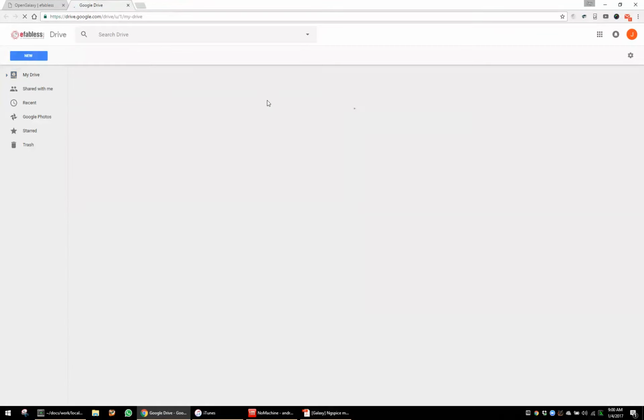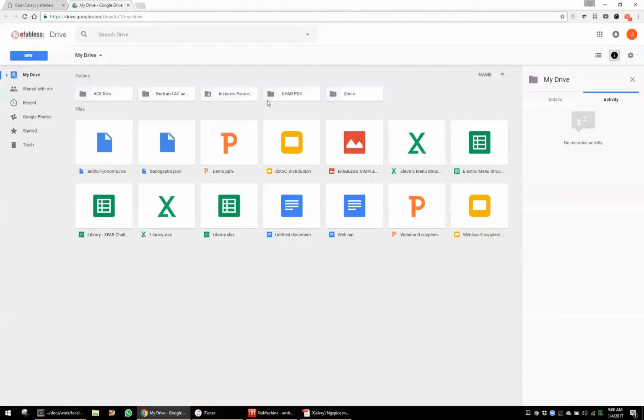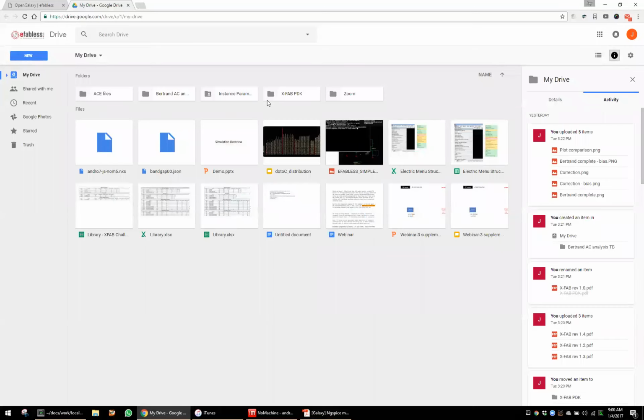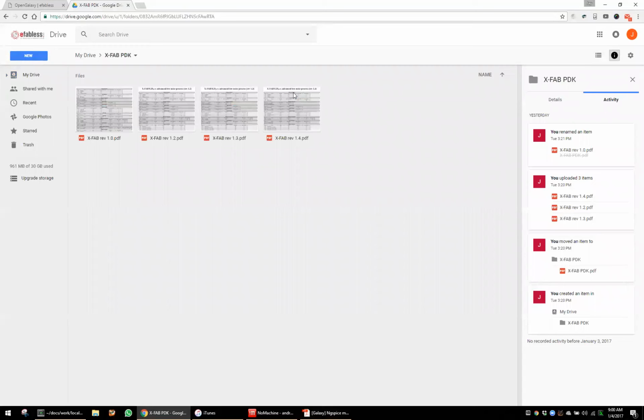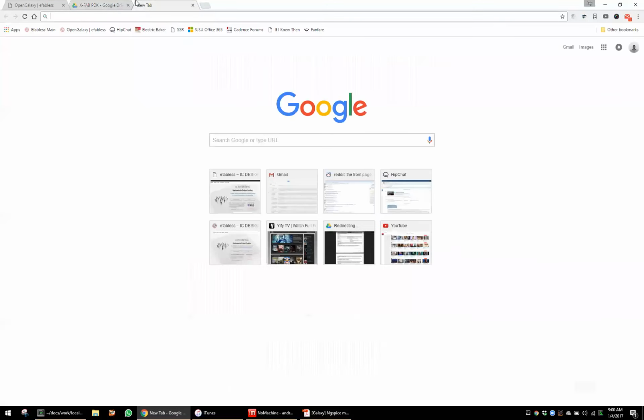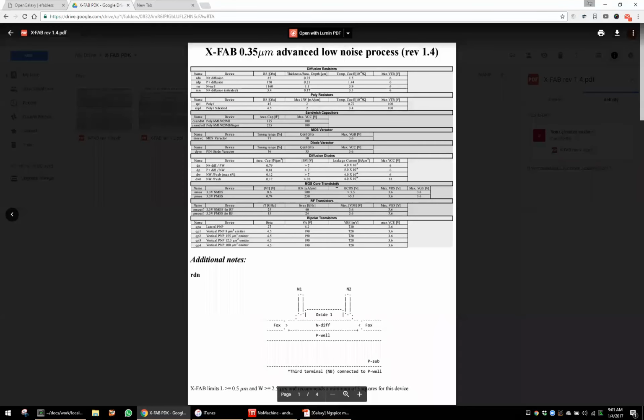I have a paper, and they say that the minimum size for the width is almost any width, but the minimum length for the well resistors is 0.7 microns. Sorry, it's 3 microns. Yes, 3 microns. But the test that you sent with the width, the 3 microns, or the 15 microns, I didn't understand.